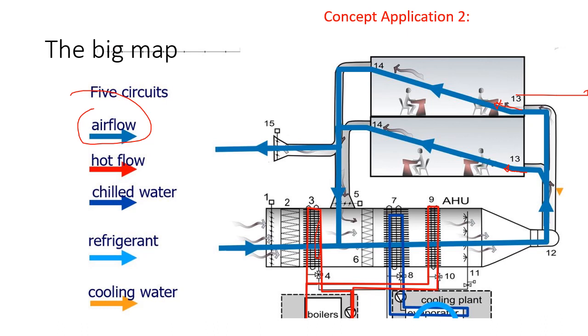And you can see this going into the cooling coil in number 7. And 8 is a valve to allow this bypass, all going into the cooling coil in summer. Right? And then this circle, we don't see the complete picture. It is a refrigerant. Refrigerant takes heat away from the evaporator and dumps the heat at a condenser to the cooling water.